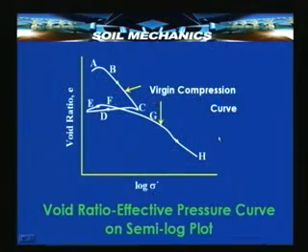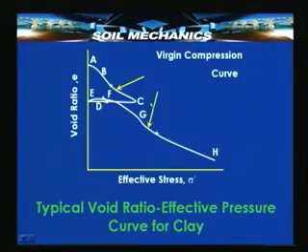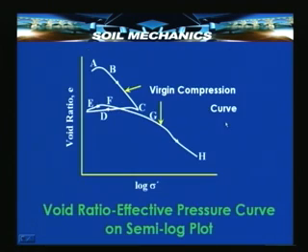But now, what is the difference between this graph and the graph which we had seen in the previous slide? We saw in the previous slide that this phenomenon is a highly non-linear phenomenon. Although it appears to be somewhat linear in these ranges, it is relatively non-linear in nature, and therefore, we prefer to plot this e versus sigma dash curve on a semi-log graph.